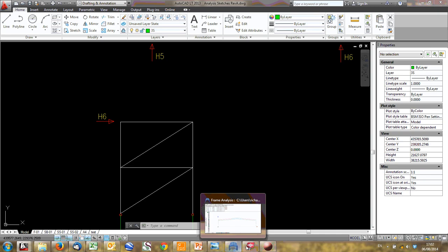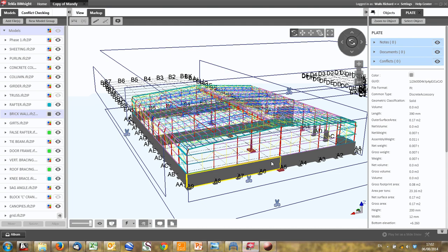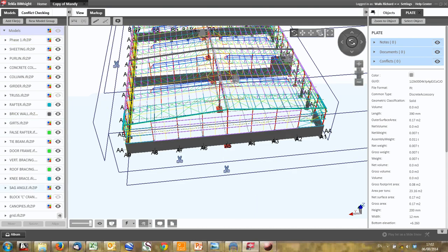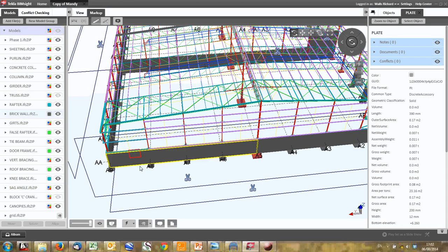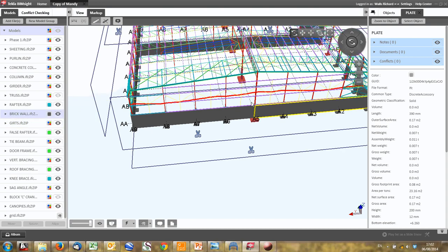Because once again, what area acts on that? If you look at it, obviously this load goes this way, this load goes this way, and some goes to the central column, some goes upwards, some goes downwards, so let's mark it up. Some load goes upwards, some load goes downwards, some load goes that way, so we divide it in half. Right, so there we go. That's the area here that gives you H6. So when you do your model, it should be more or less that.